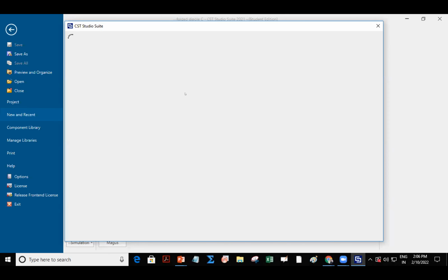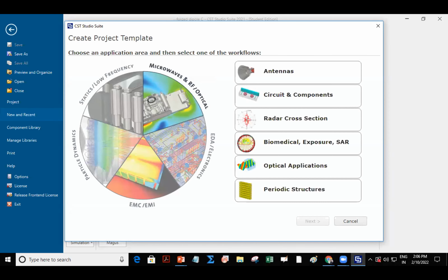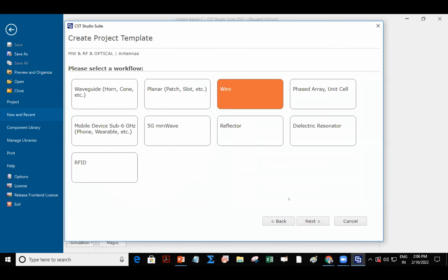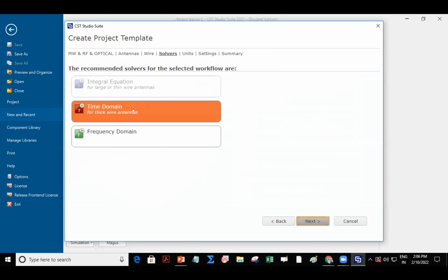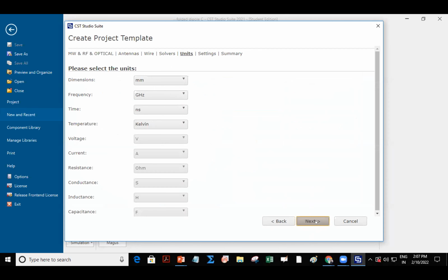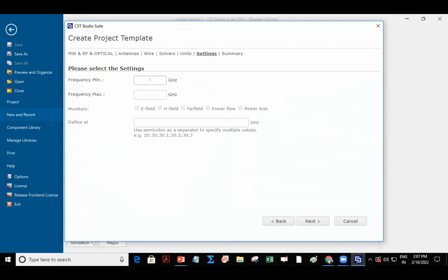What was the frequency? 2.4 gigahertz, right? Yes, sir. So let me define the antenna. I'm quickly making that. Doesn't matter if we are not able to finish it today, because actually I wanted to do a loop antenna, but that we will do later on. So let me design this here, 2.4 gigahertz. Frequency, you took it from 0 to, let's say, 3 gigahertz.